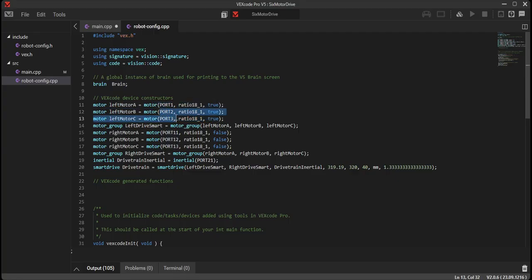So unplug 2 and 3 and leave only motor 1, the motor A in port 1 plugged in, and make sure that when you use the joystick that the wheels spin in the direction that you want them to. Then unplug this one and plug in port 2 on its own, test again, same thing for 3, and same thing for the other side.